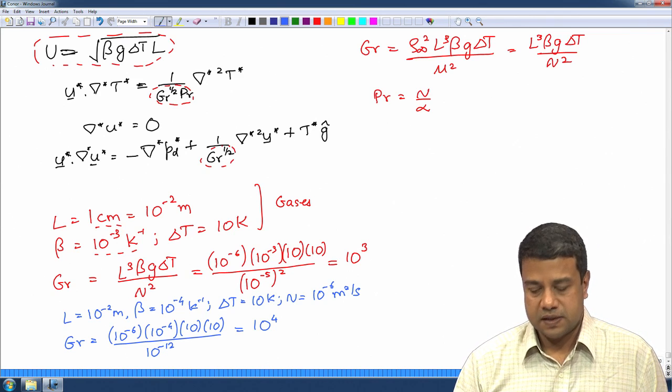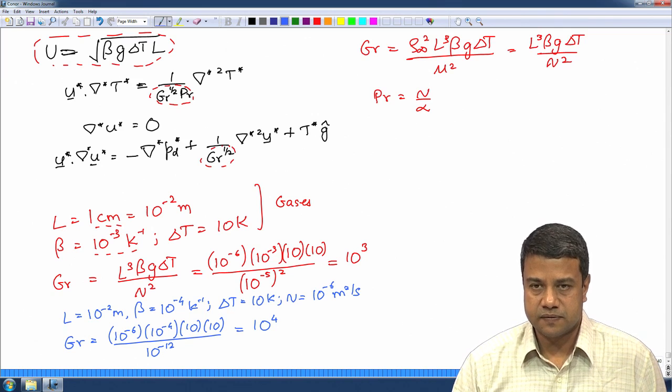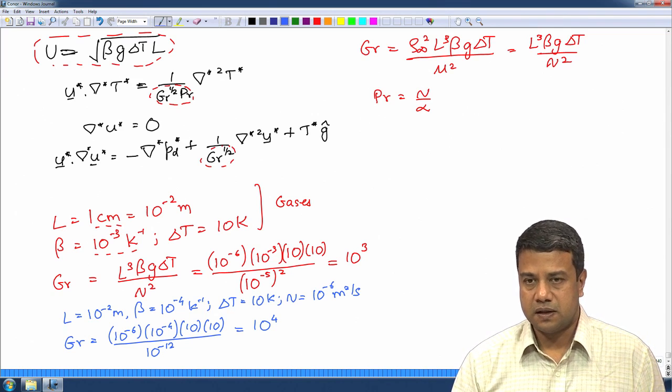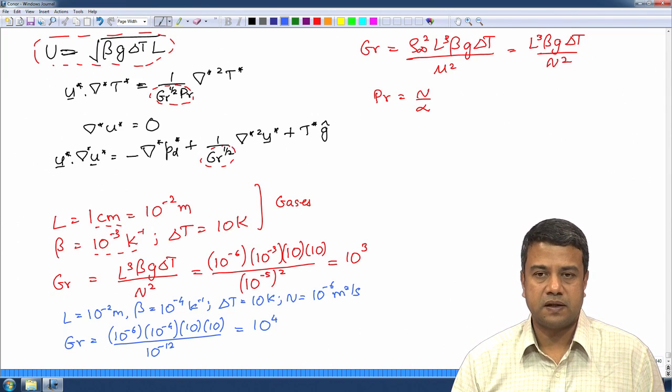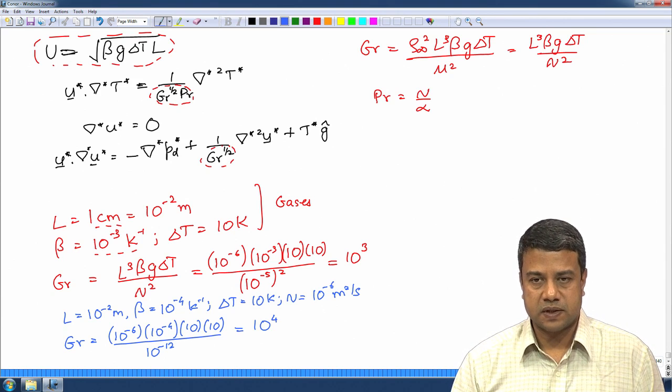In this particular case, I will derive the equations and I will scale them. I will not solve them numerically, because the procedures for numerical solution we have not yet discussed in this course. It turns out that you have to have ways of solving the momentum and the mass conservation equations simultaneously for two components of the velocity plus the energy equation, and we have not yet looked in detail at fluid mechanics. How does one solve coupled vector equations?